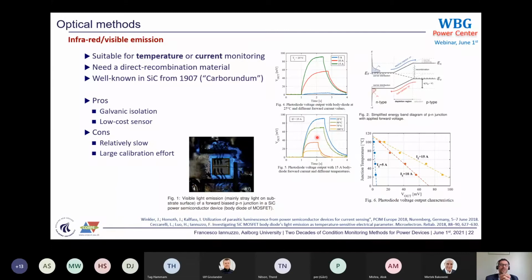So what you can do is use a visible light detector which has a very narrow optical band. If you have a very narrow optical band, you are focusing on a limited range of wavelengths. Then when your temperature changes, you are moving the emission peak and the amplitude inside this band, and you can work out what the temperature was.